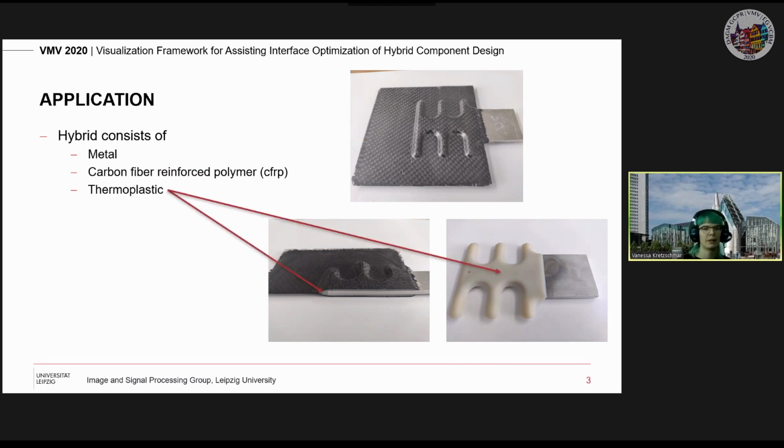There, the metal insert is further coated by a polymer, which reduces the jump in stiffness, which has been shown beneficial. The hybrid is also designed to provide interlocking between metal and CFRP, while being suitable for lightweight mass construction and designed for in-plane load scenarios.